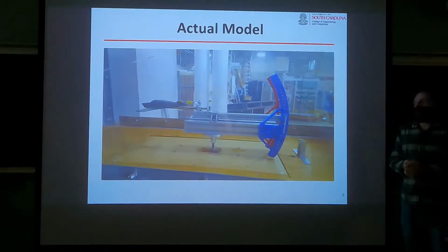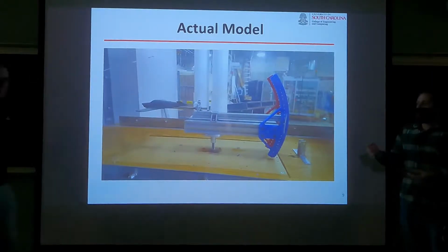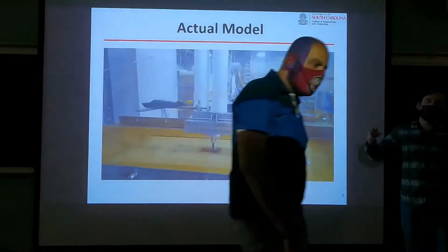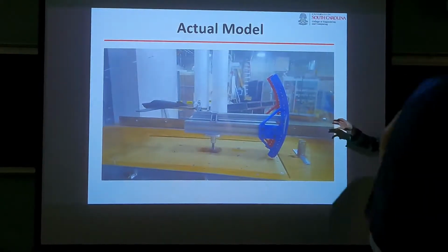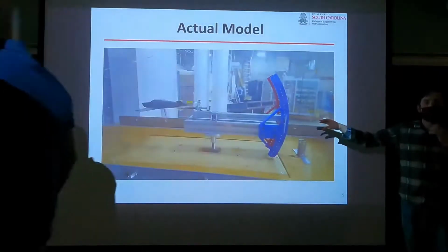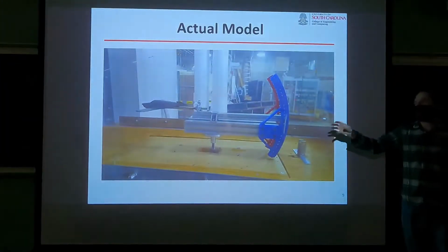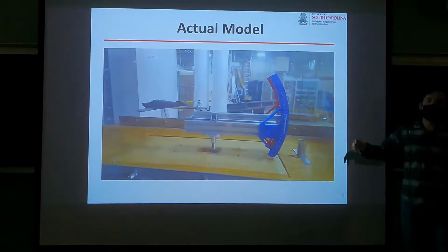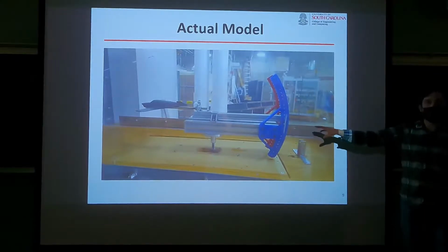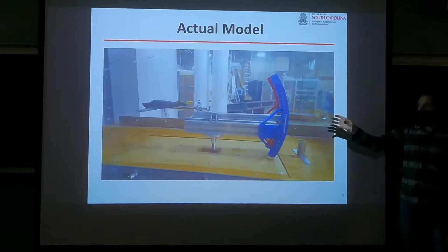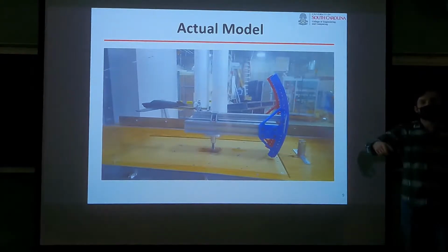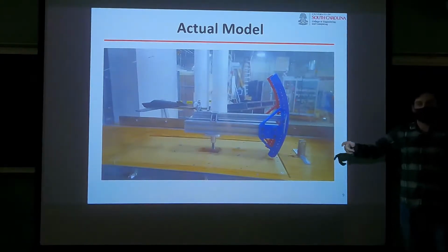In wind tunnels you typically have some blockage ratio, and that can create a lot of drag, especially from the mount itself. We're trying to find out how much drag we are creating just from having the mount in there, because we need to figure out how much drag the aircraft itself was creating, not how much drag our mount was creating.